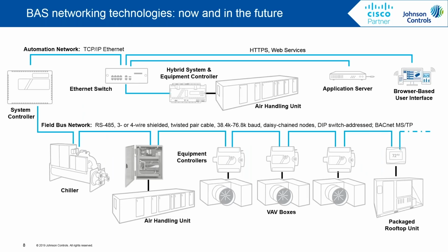So those trends really expose the weakness of using serial or RS-485 based technologies for networking the equipment controllers. Serial buses are somewhat unique to the building automation system industry, so they're not prone to being shared, the field bus network, with other building system networks. And the knowledge of field bus networks resides mainly in the building automation system industry, so you can't leverage outside expertise like our friends in the IT department or suppliers to the IT departments to help with the installation or servicing of those field bus networks.